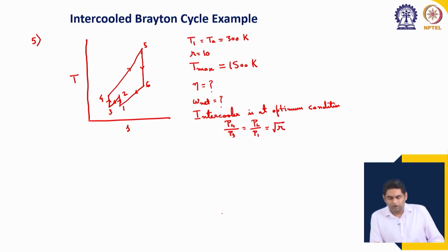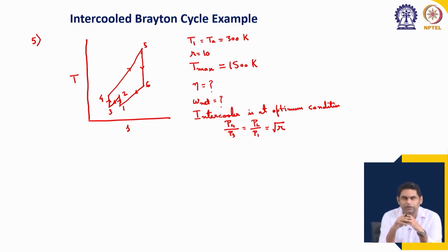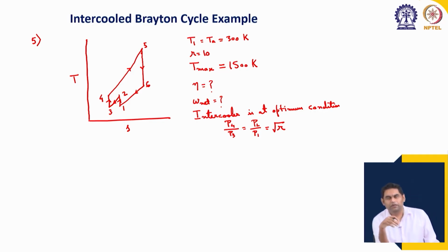So, now how to proceed? Procedure is exactly same. So, I always encourage that you should not use any of the expressions as formula. Expressions were derived to understand the characteristics and plot the characteristics, but when solving numerical problems we go step by step through each process, find out the important parameters which are needed at each state, for example, temperature at each state, and from that we can calculate all the energy transfer values.